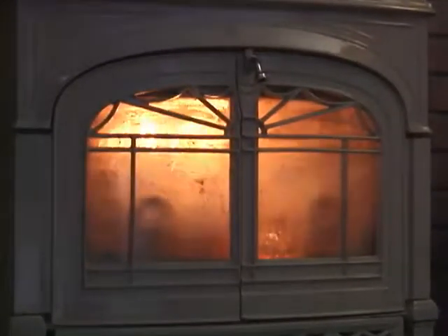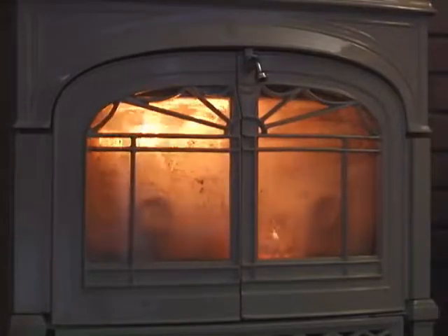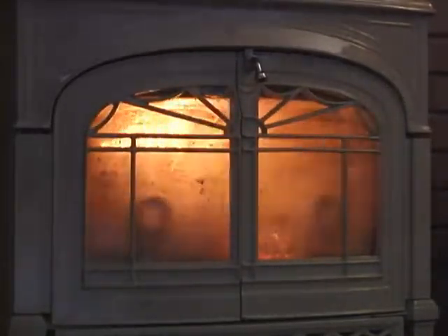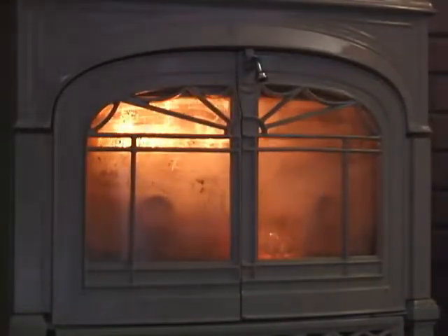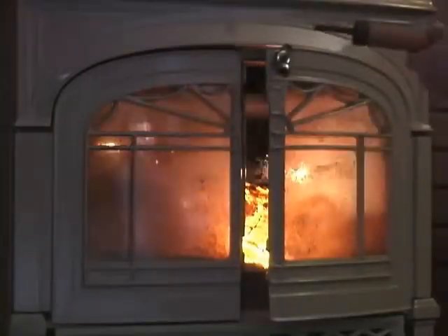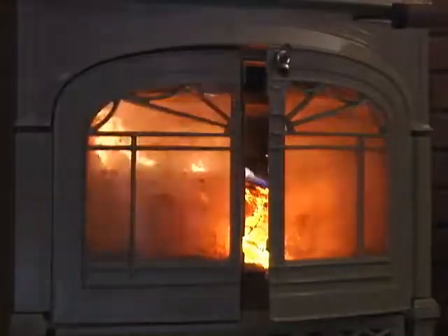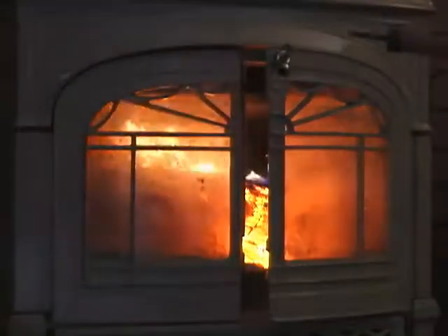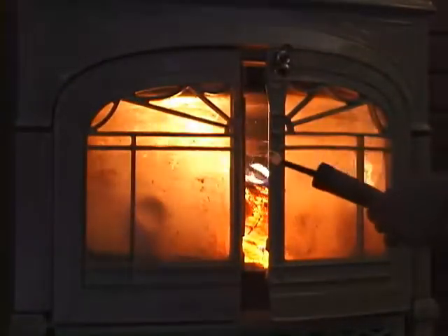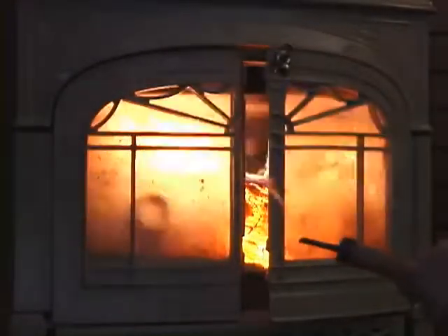Although fireplaces are not listed under the ANSI categorization system, it is useful to know that most fireplaces would fall under the Category 1 classification. They have both a negative vent pressure caused by the rising hot combustion gases and high flue gas temperature, and they are therefore subject to the many draft problems experienced by Category 1 appliances.